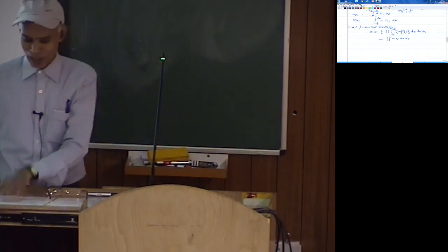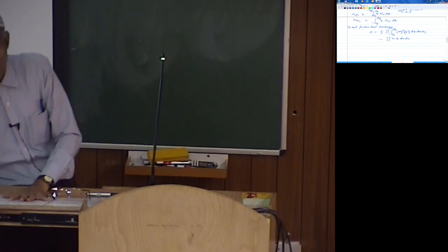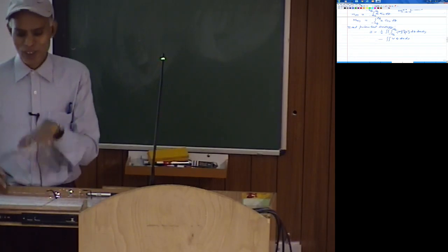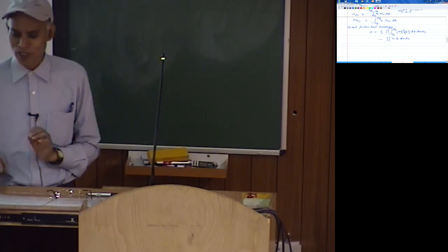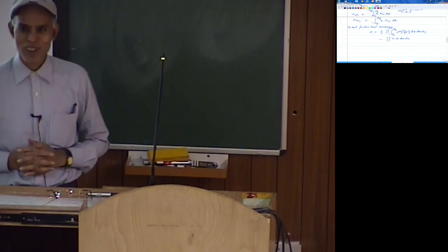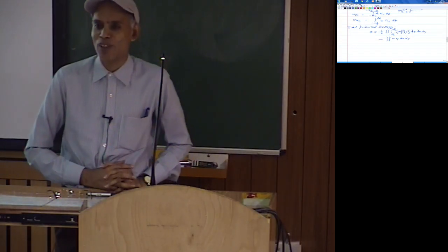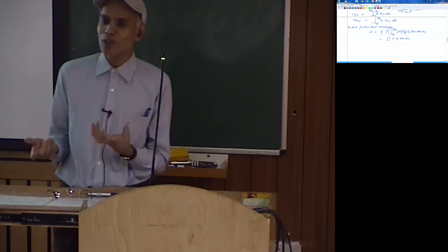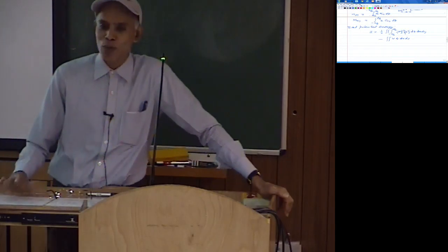There is a distributed force from the top side. There is a distributed force from the bottom side in the opposite direction. Let us say that there is a pressure from the top as well as pressure from the bottom, and the two pressures at the top and the bottom are the same. So then, as per this theory, what would be sigma xx, sigma yy and tau xy? 0, because Q is 0 effectively. This Q and the other Q actually cancel each other. So net force in that case is 0.